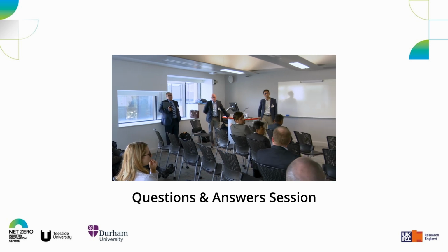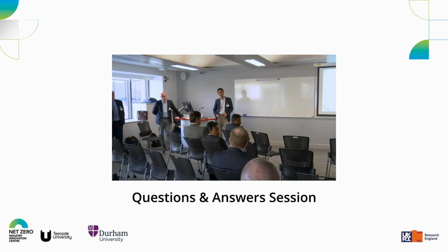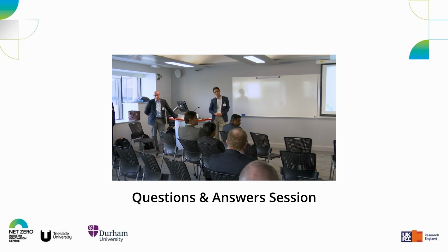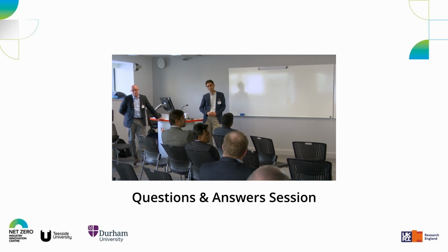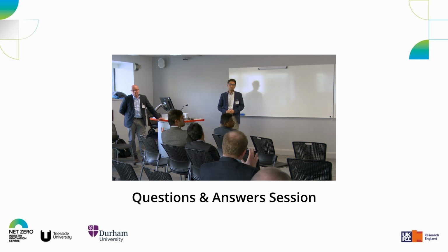Yeah, it's Dogwin with Pensad. We had a chat before, and it was a very interesting presentation. But the fatigue analysis, did you consider a pre-existing planar flaw in the pipeline? A lot of the work we do with pipeline operators, the fatigue looks good on an S-N case where you consider there are no imperfections, but once you consider that imperfections could behave like a crack, that's when things get more interesting. So I was wondering if you did that and whether it's in your consideration.